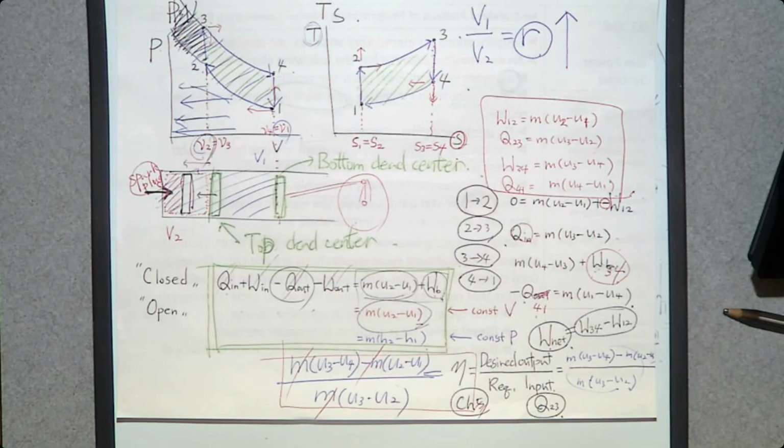The problem is that you have a fuel here that will experience high temperature, high pressure. What about if you don't have a fuel, just air? Can you compress further? Yeah. Is there combustion? No, air cannot undergo combustion alone. So let's just add air and compress as much as we can. So we can achieve extremely high compression ratio. Then when it is extremely high pressure, let's inject fuel.